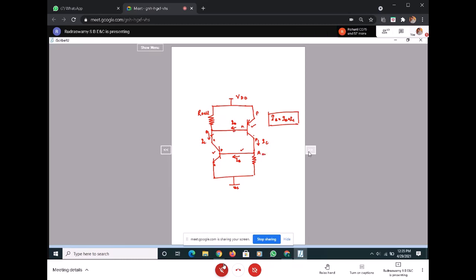As I said, because of noise, if I assume that there is 0.7 volts at this point, and there is a base current appearing, and if the base current is somewhere around 1 microampere, and if beta is, instead of 50, something like 25, the collector current will be simply 25 microamperes, and this acts as a base current for the NPN, sorry, PNP, and this in turn gives rise to 25 times 25 microamperes base current for an NPN transistor.